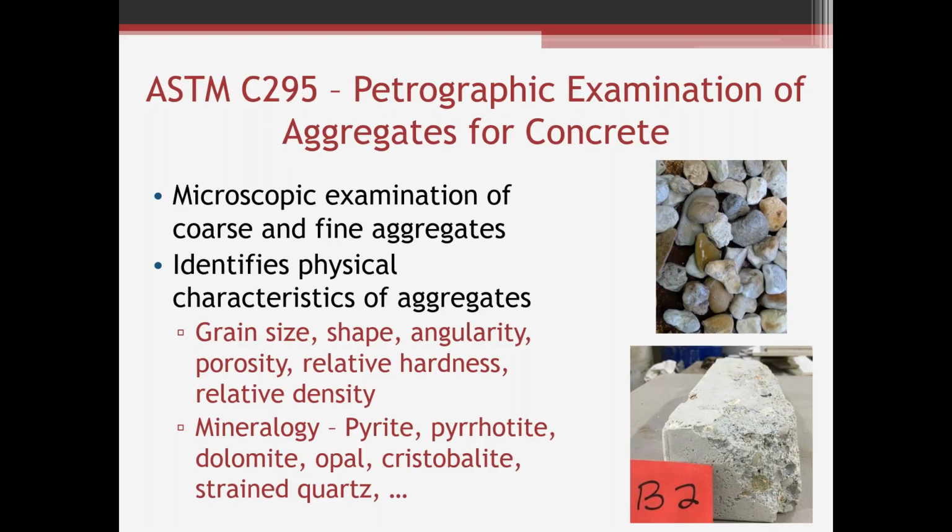Maybe you do a quick petrographic examination to look at the physical characteristics, to see if any of those characteristics are present that might lead to deleterious reactions or poor performance.